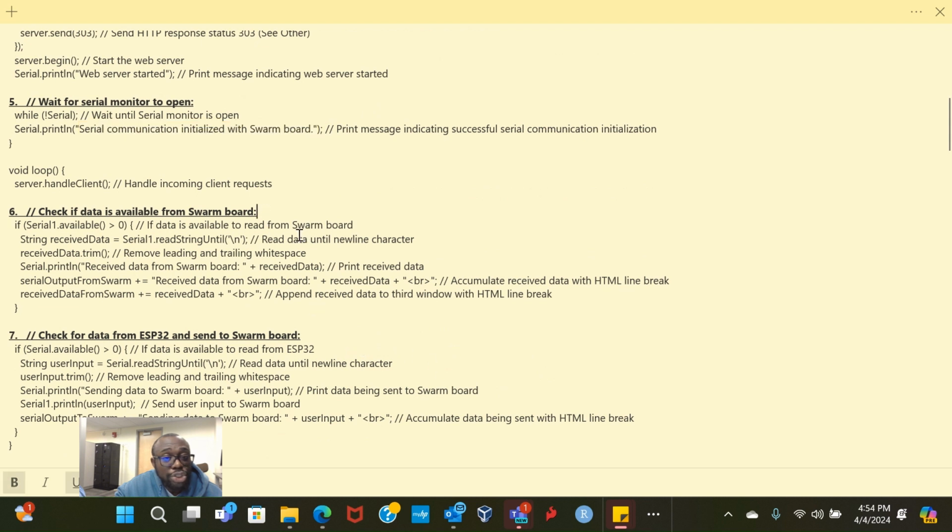Then what I have to first check is if I've received any data. The Swarm board periodically receives messages coming from the Hive. It's a client-server architecture. Once you purchase the Swarm board and the contract to send messages, when you send a message over the satellite constellation, it gets to a Swarm Hive, which is hosted by Swarm, and from there you can have cloud access to that server to get information and also send. So it's two-way: send and receive.